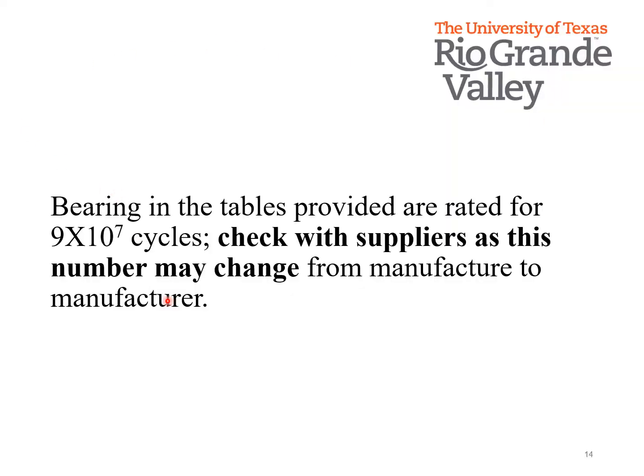So here I do want to remind you that the bearing tables provided are for 90 times 10 to the 6 cycles, but these are for the bearings that are in your equation booklet. Once you go out to the field and you're picking bearings from the different suppliers, you want to make sure you double check with that bearing supplier or the bearing manufacturer to see what is the rated life that they're giving for that bearing, because the number might change from manufacturer to manufacturer.